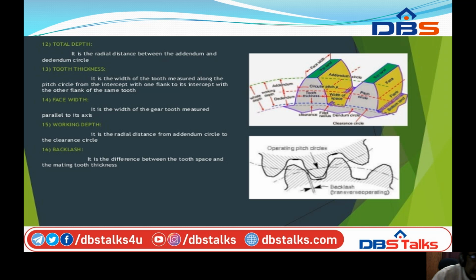Then total depth. It is the radial distance between the addendum and the dedendum circle. Then tooth thickness. It is the width of the tooth measured along the pitch circle from its intercept with one flank to its intercept with the other flank of the same tooth. Then face width. It is the width of the gear tooth measured parallel to its axis.